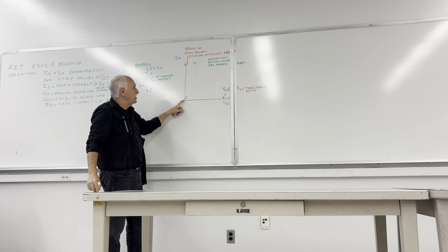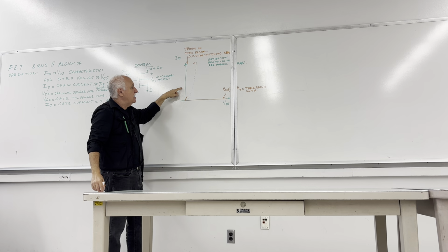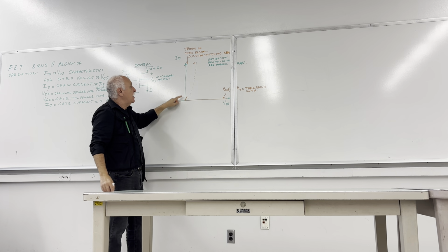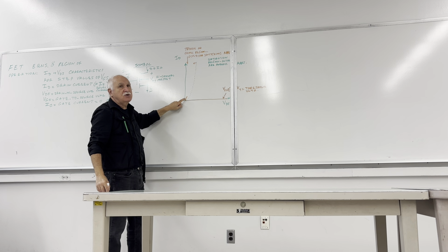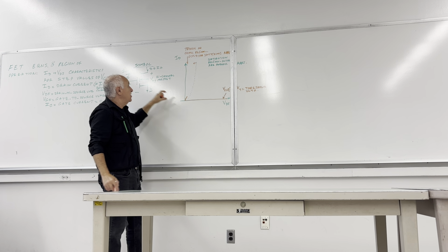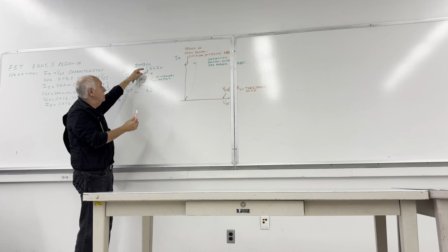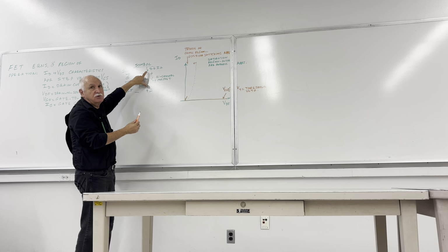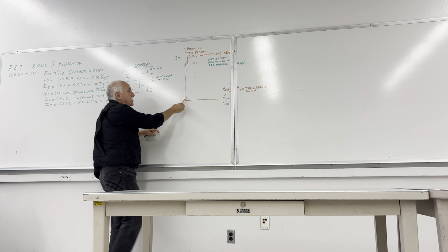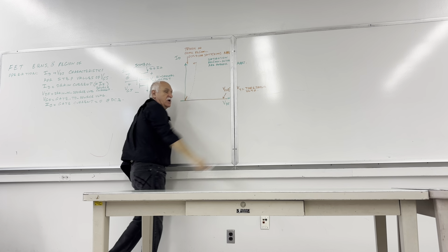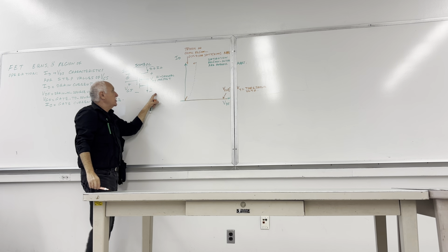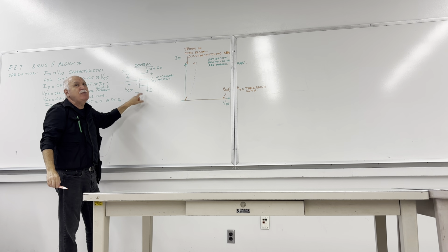Initially, it will be a linear relationship between ID and the VDS. That is why, starting from the origin, this region picks up like the characteristic of a resistor. If between drain and source we had a pure resistance, current would be proportional to drain to source voltage forever. But it doesn't happen because this is a semiconductor.